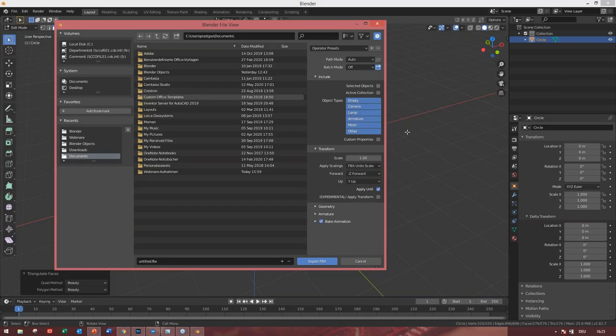And that's very important for Pandoras Box if you are working with marker calibrations in the Warper. Then you have to create an object that's matching the real 3D object, so in the same size. So that's very important for this part. Z minus is forward, and Y should be up, because Y is always up in Pandoras Box. That's already set. And now we can export it.